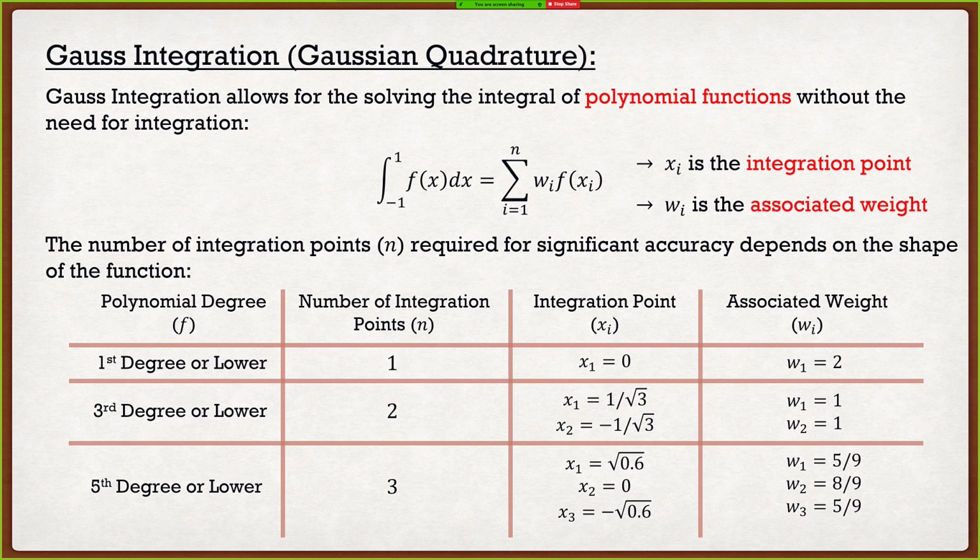Because you guys can do that. There's nothing holding you back. There's no math police coming knocking at your door. So if you guys want to do that, you can. And then as you guys will see, it won't give you the exact solution, but it'll be a good approximation. And if you think about Abaqus, when we talked about reduced integration, that's exactly what reduced integration is. Instead of using 2 integration points like I should, let's say I just used 1. But we're going to talk about that, so don't worry.